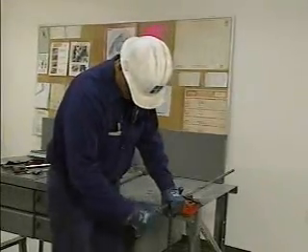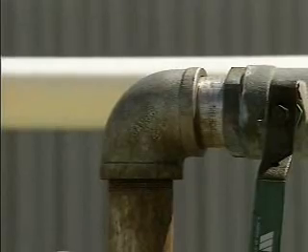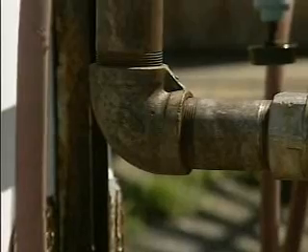After all burrs and ridges have been removed, wipe the pipe clean, inside and out, with a rag. Shavings left inside the pipe can contaminate the fluid in the system and clog filters or other components in a piping system. A variety of sizes and types of individual pipes can be connected by joints and fittings to form a larger piping system. Before the pipe can be installed, the length of the pipe that you need must be determined. The pipe must be cut to size, and the pipe must be threaded. In this part, we'll see how to use a pipe die to cut threads on a pipe.